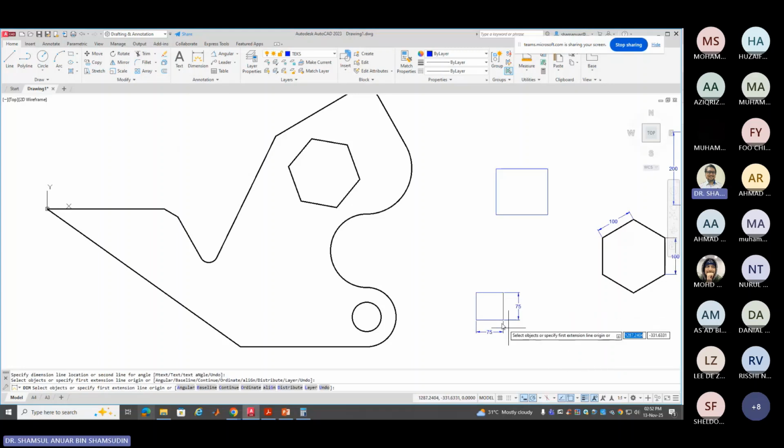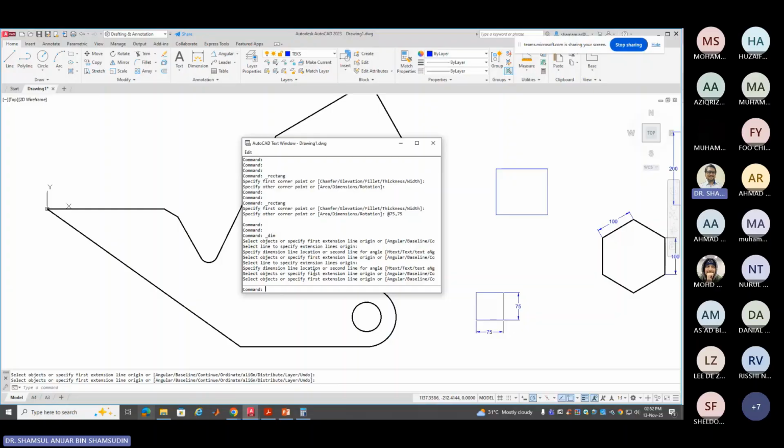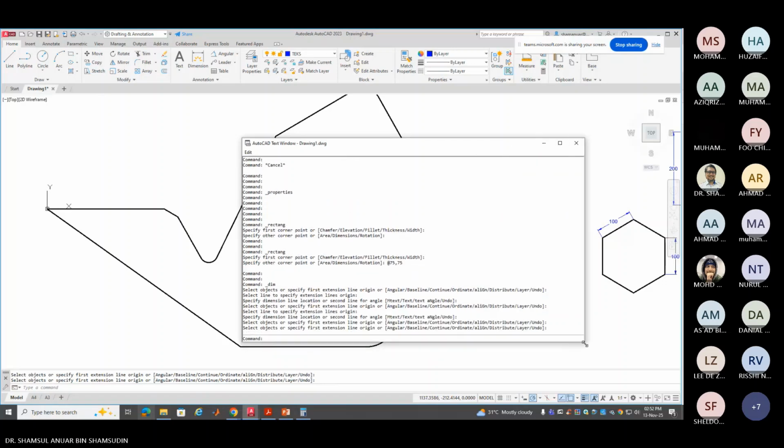If you click anywhere at a random point, your coordinate command must have that @ sign. So if I click on F2, so like this one, I have to have that @ sign or alias sign before I do that.